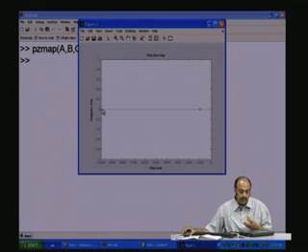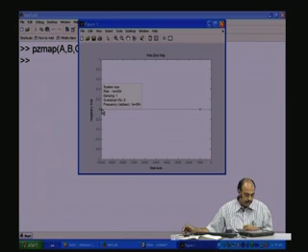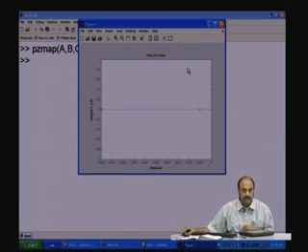In fact, now you can place the pole accordingly so that you get an idea of what these damping things are. The character of this pole here, the overshoot would be 0%. If you place it here, damping is 1, and you get the frequency and the pole positions. So, you can position the pole accordingly on the pole-zero plane and then get back what should be the R and C value such that you get this pole condition, and thereby you can design your circuits.